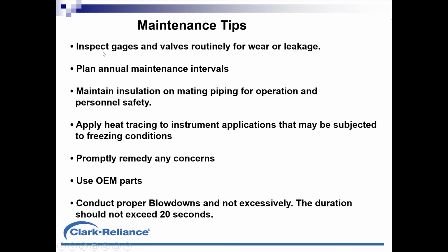To touch on some maintenance tips for you today, all these devices should be inspected regularly and valves routinely to look for wear or leakage. Any steam leak should be remedied as soon as it's discovered. If steam leaks are allowed to persist, the result will be damage in a cavity of a valve, which will require replacement, maybe damage to insulation, packing, valve stems. The cost of the repair escalates if the item is permitted to leak for an extended period of time.